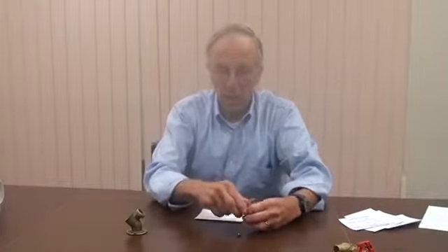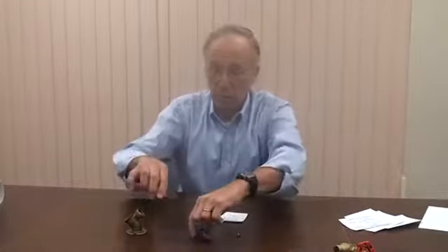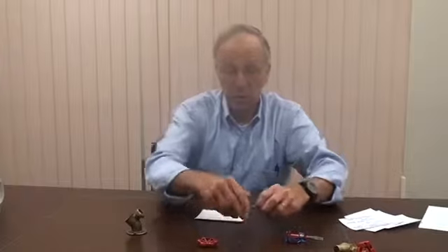And what I'm going to do next is take off the handle, and this is held on by a screw. Take that off. And of course the purpose of this is to hold the handle on the valve stem. And that valve stem is square, and the receptacle end of the faucet handle is also square. So they match up. So now each of these parts has that function.